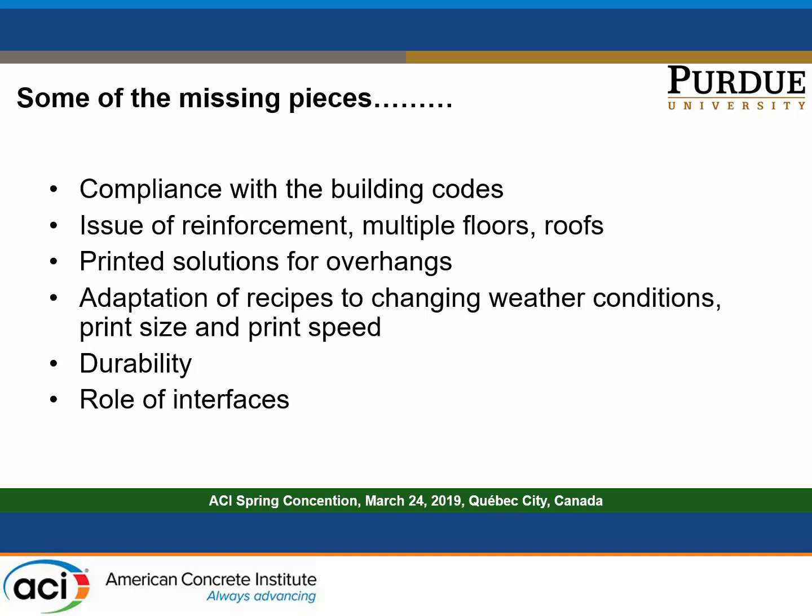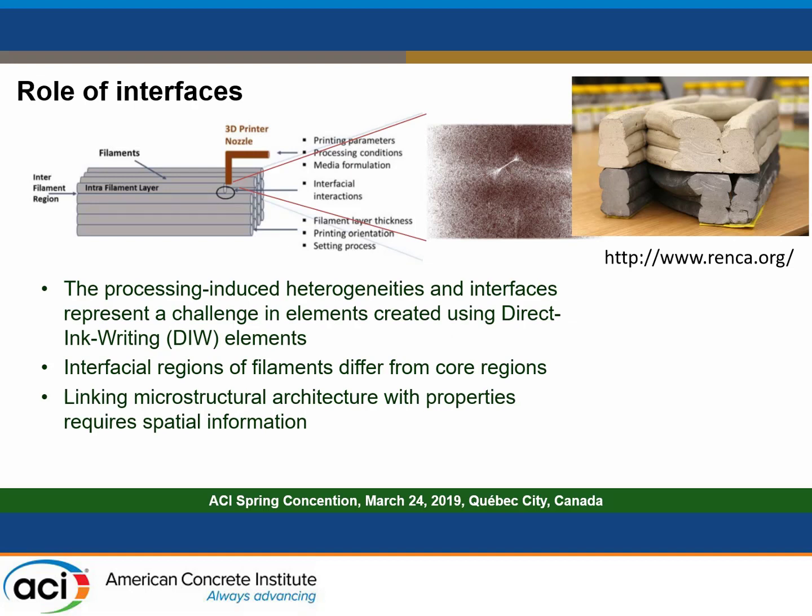Durability is another big problem. If you do layer by layer printing, you have naturally occurring cold joints, essentially interfaces that will have different properties. There's lack of continuity there. How do they influence the behavior of the element? So that's one of the areas of research that we are specifically focusing on. We are looking at the role of interfaces and the heterogeneities introduced by those interfaces, and how they influence the behavior. And there are various approaches.